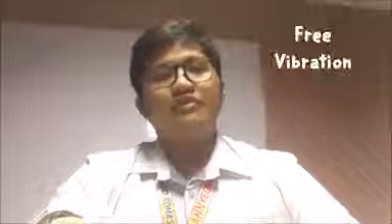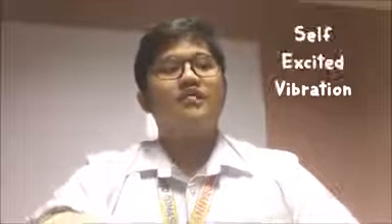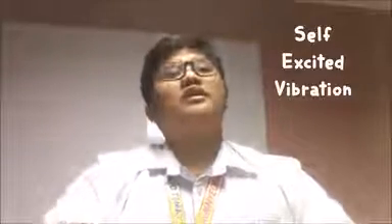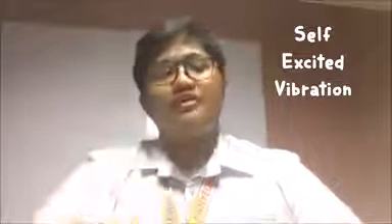So, chatter or vibration. This is the mechanism by which a process dissipates energy in elastic deflection. There are 3 types of vibration, namely free vibration, forced vibration, and self-excited vibration. You will see the 3 types of vibration on the figure on the right. So, what is free vibration? Free vibration is the response to any initial condition or sudden change. Amplitude of the vibration decreases with time and occurs at the natural frequency of the system.